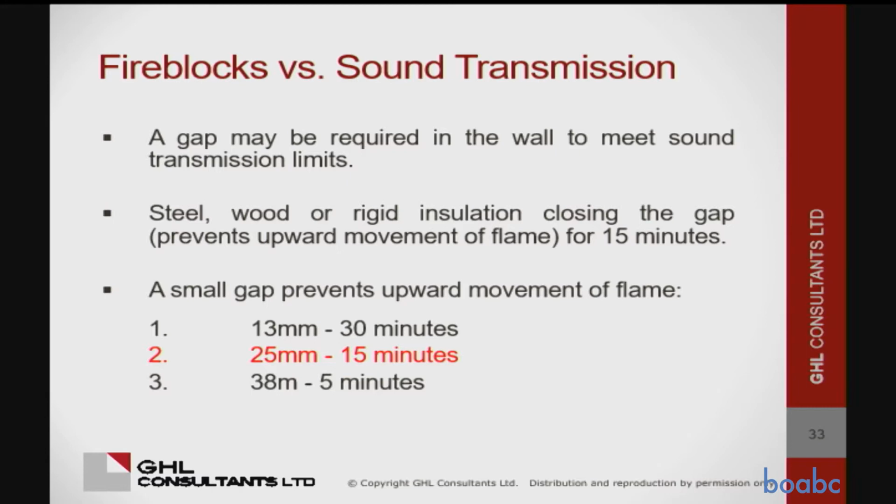So the gap has all been tested, and a 13 millimeter gap will limit fire spread for 30 minutes, and a 25 millimeter gap for 15 minutes, and a wider gap for a shorter time, obviously. So obviously the code picked the 25 millimeters for the 15 minutes because it says a fire block has to be 15 minutes, and if this gap works for 15 minutes, then it's the same thing.